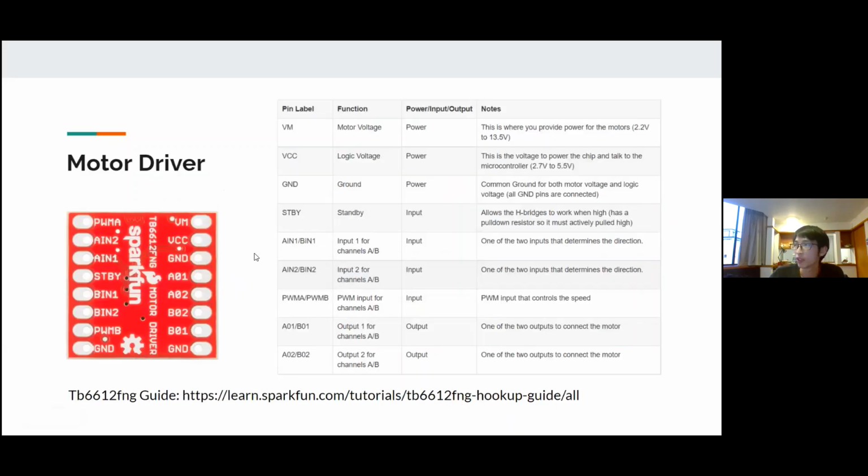That is equivalent to a digital write with a value of high. If you put 255 for PWMA, it will be full power supplied between these 2 pins, and that means your motor is going at full speed.